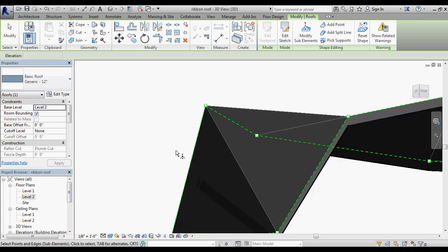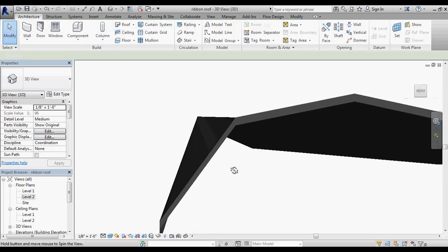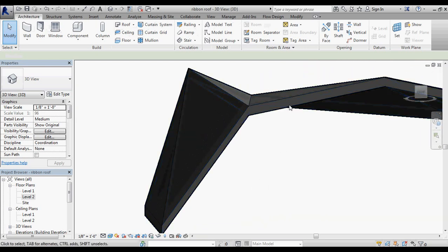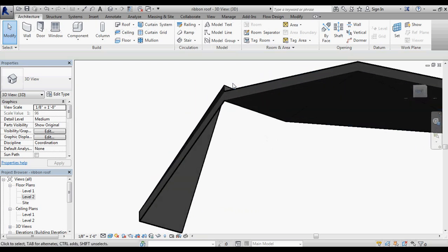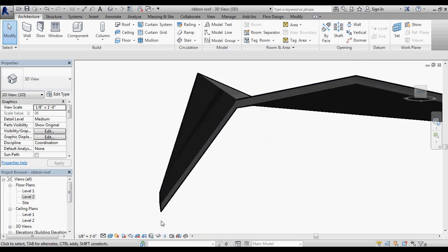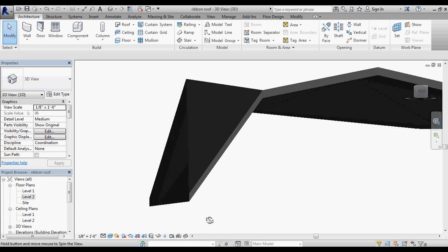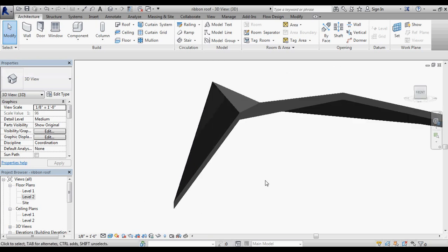I actually get a pretty big problem with my model, and that is that this edge right here is definitely thinner than this edge because it's not rotating this axis around. It's not truly folding that down across this edge. It's sort of keeping this fold on the XZ axis or the YZ axis, and it's simply pulling that edge down. And that's really creating some problems with the geometry.